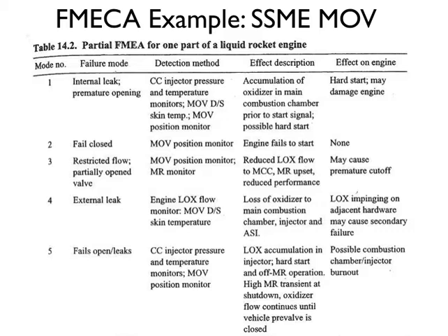If you're interested in searching on that, which you will be at some point, you want to set your FMECA up in some way that you can actually make it searchable. And I would suggest having a couple of columns to be able to filter the data, whether in the same column or in separate columns. So the mode number would essentially become a few different columns. You could have the first column be the subsystem. Depending on how big your system is and how many levels of hierarchy, you may have a secondary, more of a subsystem level or even a component level category next.